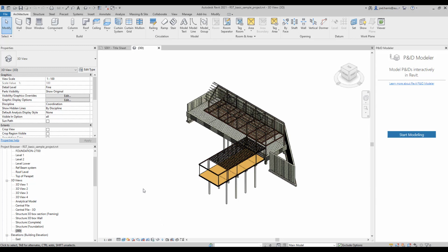Exporting a DWG file from Revit so that it can be used in AutoCAD Plant 3D is a fairly simple operation. The main thing is to make sure that you've reduced the level of detail in your Revit view and that you're in a 3D view, shown here, of the model so that the geometry you expect to be exported will be exported in 3D. In this case, if I had any small holes or layers that I could turn off, geometry that wasn't necessary for AutoCAD Plant 3D, it will save you a lot of time in orthographic generation as well as in overall model performance.